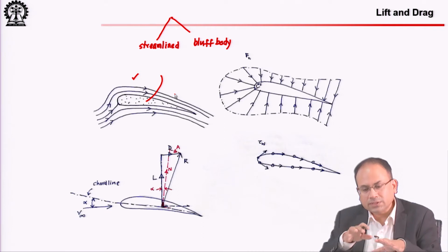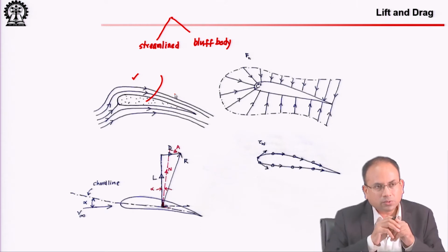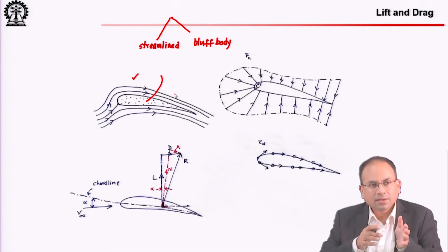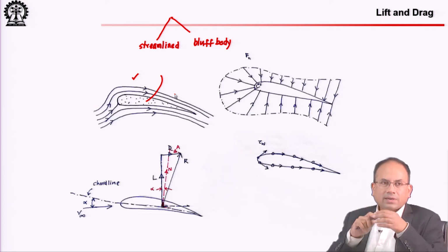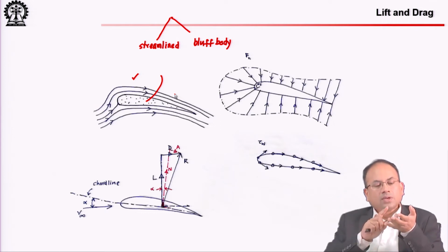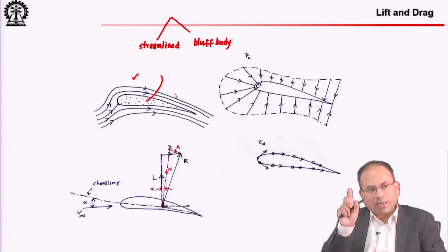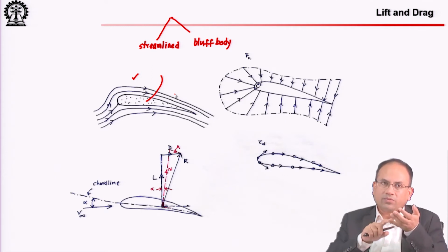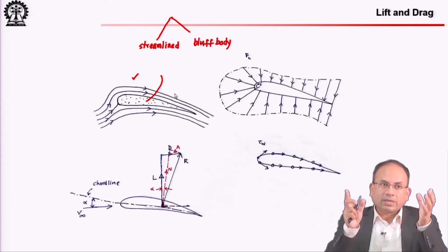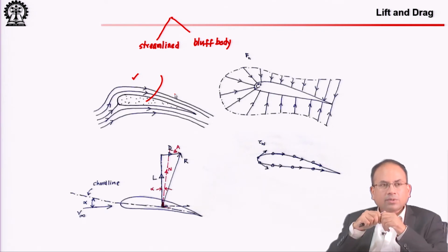At the end of this discussion on drag, I will talk about a classic experiment that shows you the difference between the drag on a streamlined body and the drag on a bluff body, and that we will do when we have studied the avenues of producing drag. These are pressure drag due to flow separation, skin friction drag, wave drag, and in real applications where wings are finite and you have trailing vortices from the wing tip, something known as the lift induced drag.